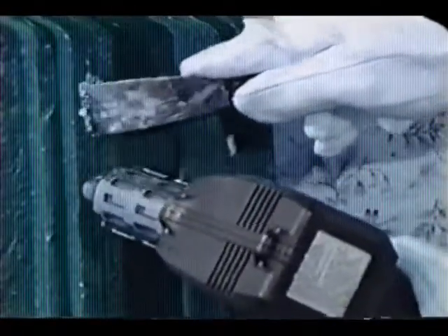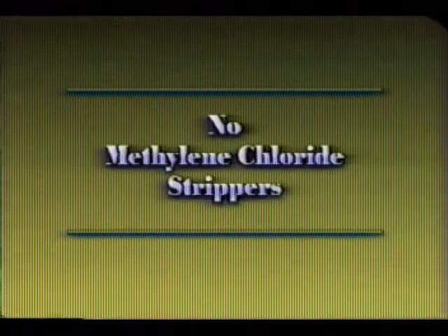Components that cannot be removed may be treated in place with chemical paint strippers or a heat gun. Open flame burning, however, should never be used because this process produces toxic fumes. Strippers containing methylene chloride are not recommended and are prohibited in a number of locales because methylene chloride can cause liver and kidney damage, carbon monoxide poisoning, and is suspected to cause cancer.